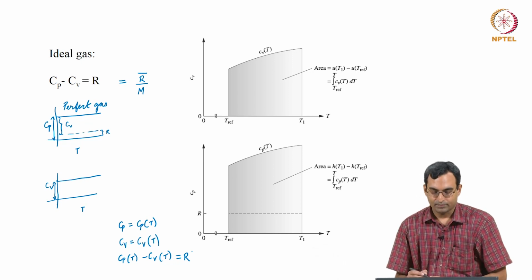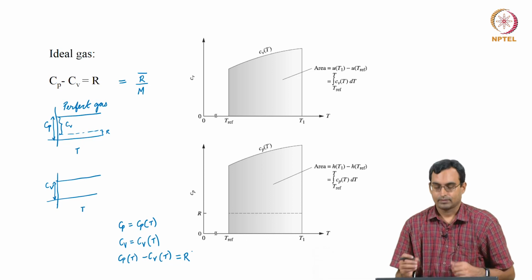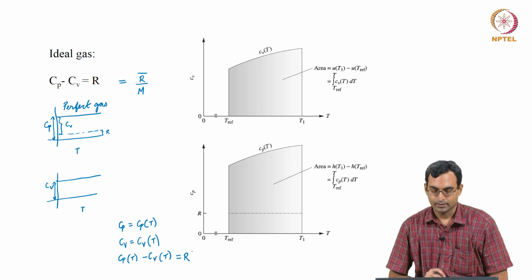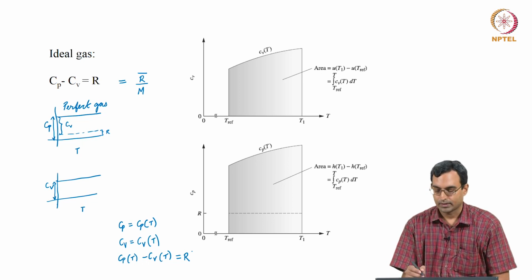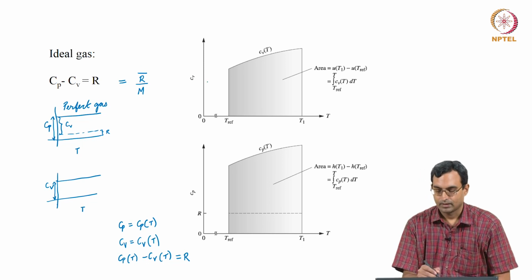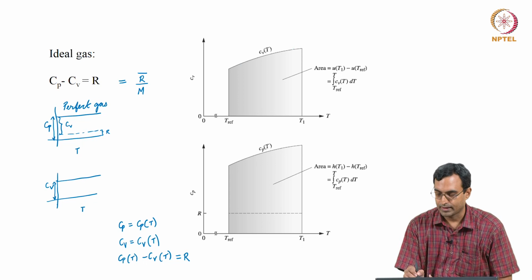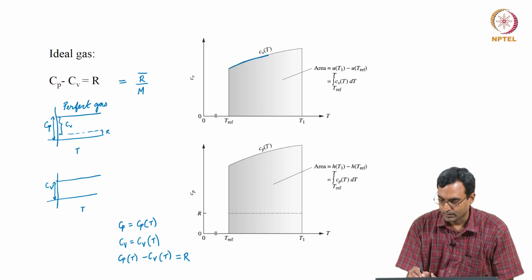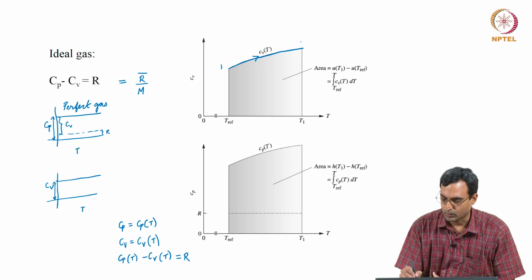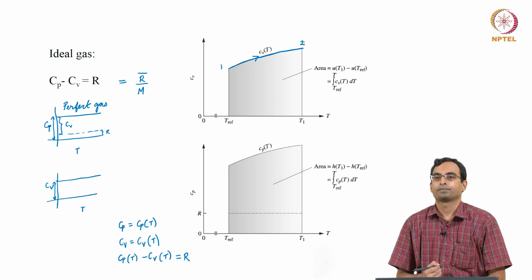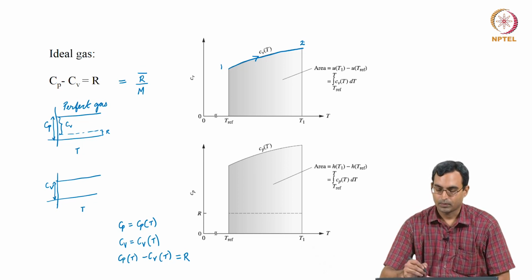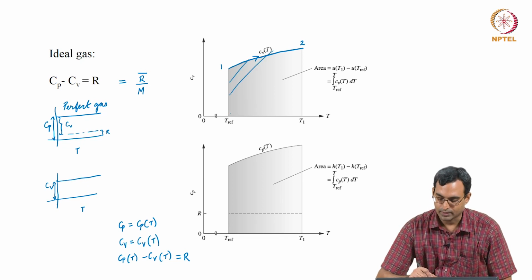So, if I wanted to find out the variation in Cp and Cv, I could look at tables and find out how these vary. Now, if I was to plot Cv versus T or Cp versus T, I would get a graph of this kind. So, here I have Cv, and this curve over here shows, for example, the variation of Cv versus T from some point 1 to some point 2, it looks like this. If I was to take the area under this curve on the x axis, what I am doing is essentially integrating whatever is under this curve.